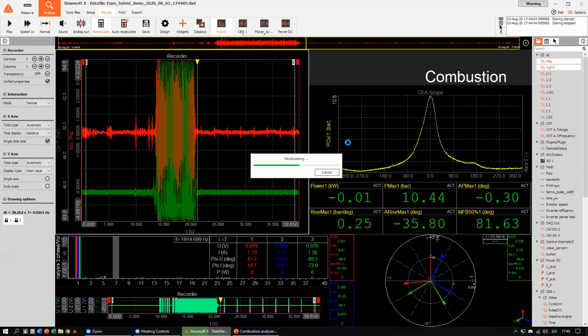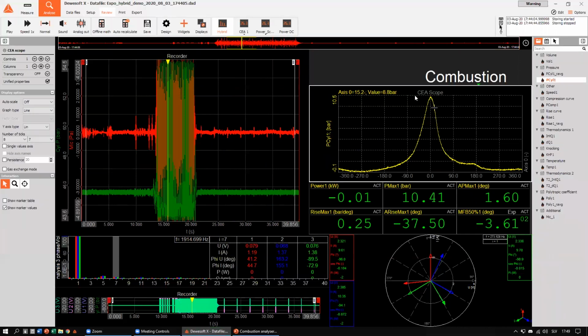So this is really nice if you are measuring fuel pressure or oil pressure, and then you want to analyze if you have some spikes from the frequency disruption of the engine as it's running. And you can add any kind of channel. You can even add measured channels from power analysis, or directly the measured power and current values, as additional channels.